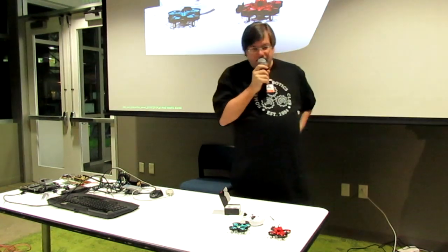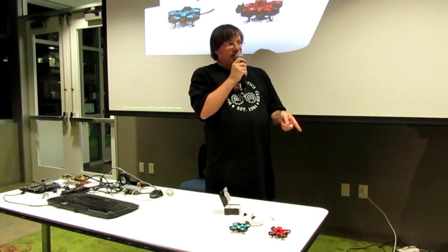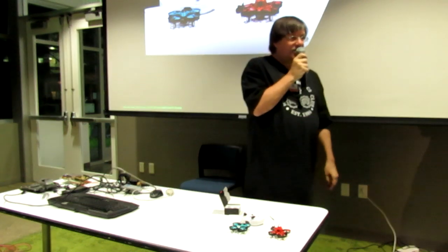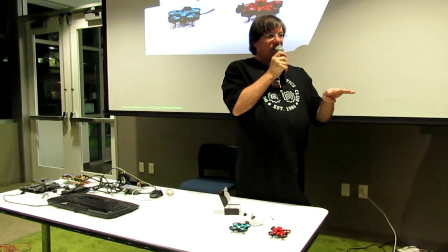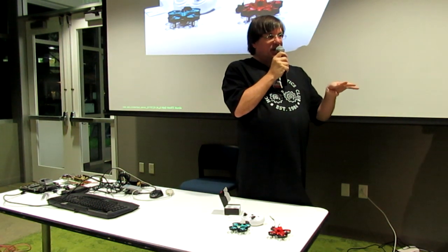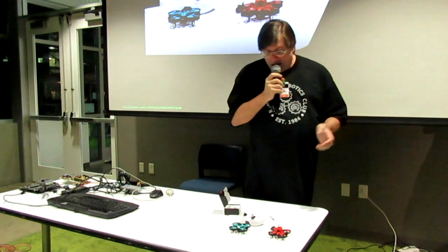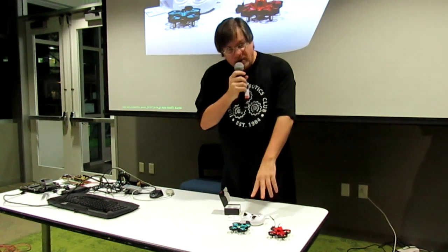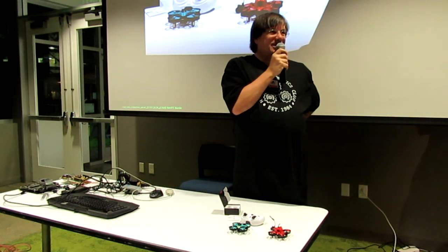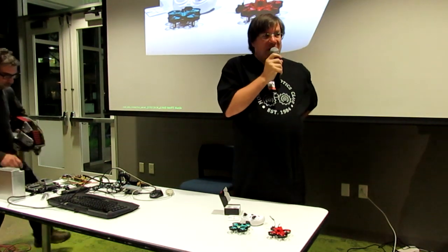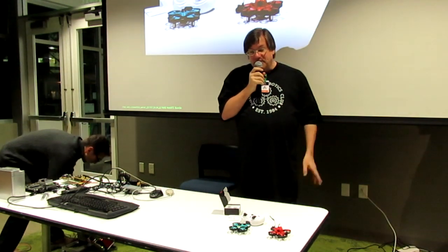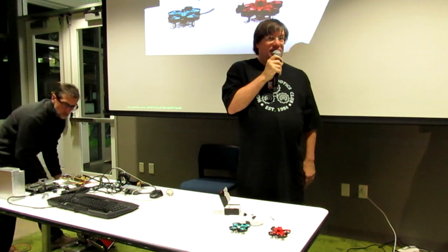No, I'm talking to an Arduino over the regular USB port, sending serial commands to the Arduino, and by varying 4 analog voltages with PWM signals and a resistor, that's all you need. It's controlling the joystick. Oh, you're hacked into the joystick. Yeah. So it's a really simple circuit. It's 5 cents worth of parts, well, plus your Arduino, and that's all there is to controlling your own little drone. It's a lot of fun.